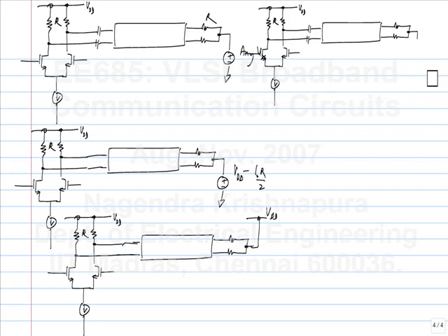And also, okay, the last one is, so I'll show it here. So in this case, you, let's say, leave it open. I mean, that is like the high impedance. An extreme case of high impedance is you just leave it open. Okay. Or you can show a very high R high, in which case you can intuitively see that it can be connected to any Vx, because Vx will not affect the output voltage. Of course, this I am talking about again DC coupled case.